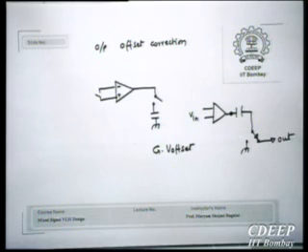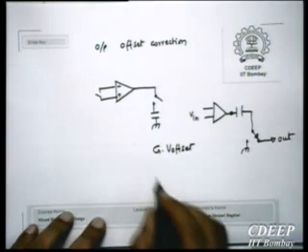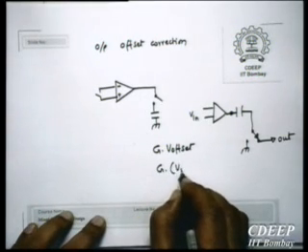Now suppose I connect the V input. What is the input that is seen by the comparator? It is V in plus V offset, and that whole thing is multiplied by G. So in the active cycle, the output is G times (V in plus V offset).